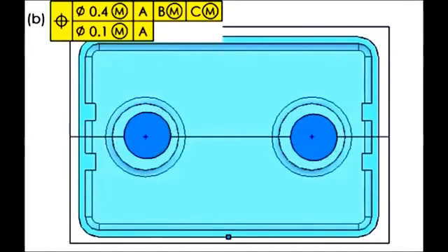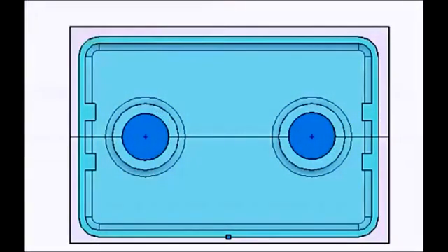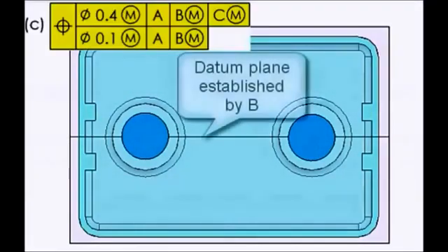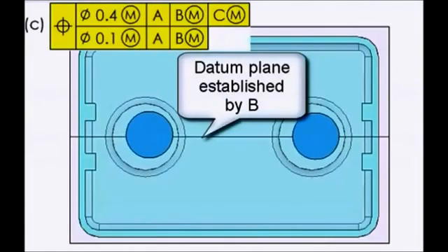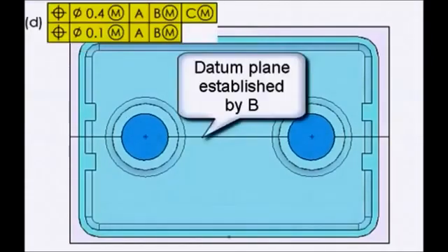By bringing down datum feature B, though, we can stop this rocking. So the pattern must be now within 0.1 to each other, perpendicular to A, and the orientation of the pattern cannot be off by more than 0.1. They can still move around 0.4, however.